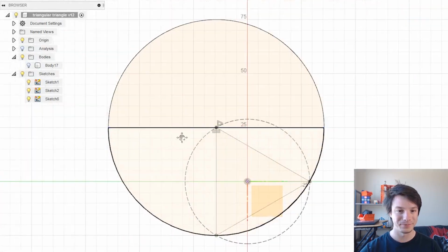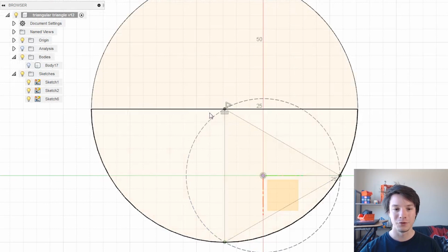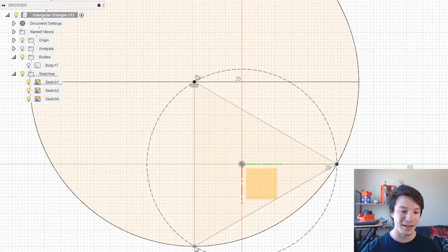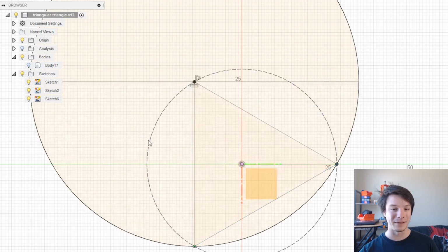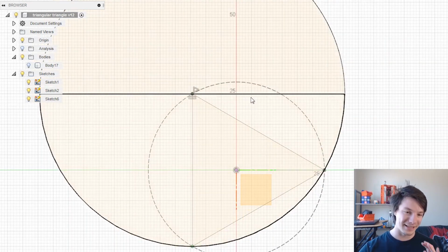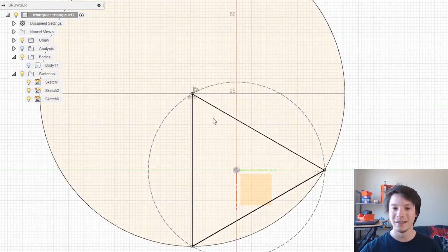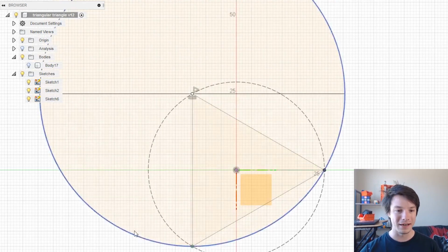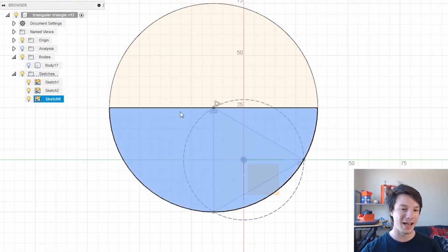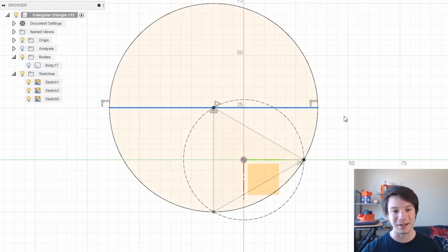Top plane. Okay. So this is a sphere drawn at one of the corners of our triangle. And like I've shown in my previous solids of constant width tutorials, it has to pass through the other 2 corners of the triangle. In this case, it has to be an equilateral triangle, and it's going to be quite a large sphere, and you need an axis that you can rotate this sphere around to create a solid, so that's why this axis is here. It could be anywhere bisecting the center point, but that's fine to me.